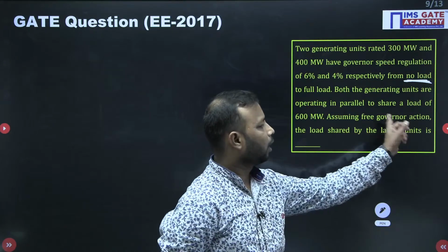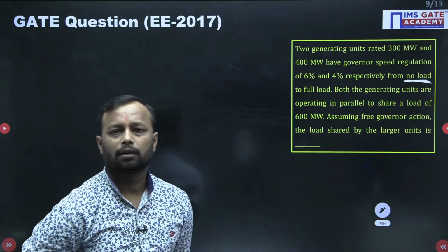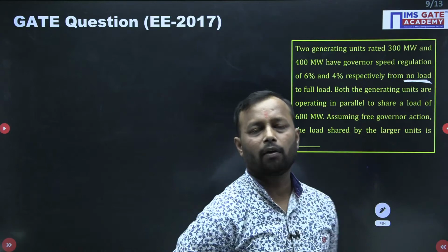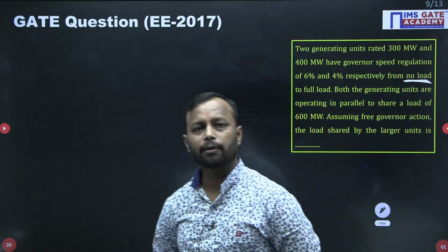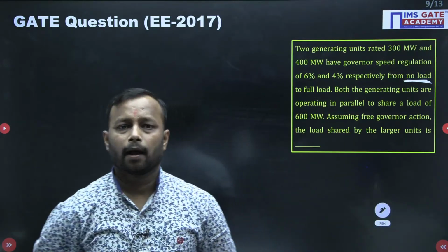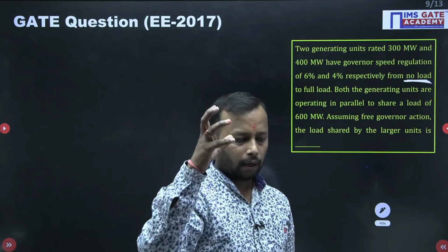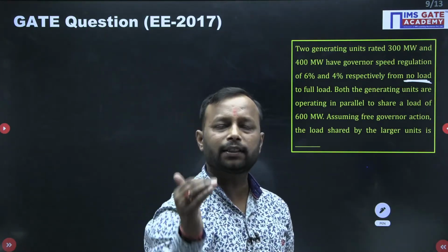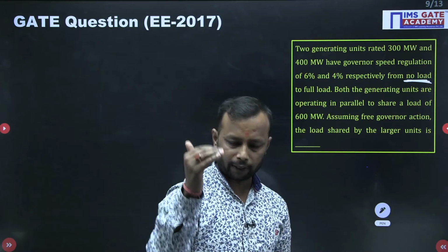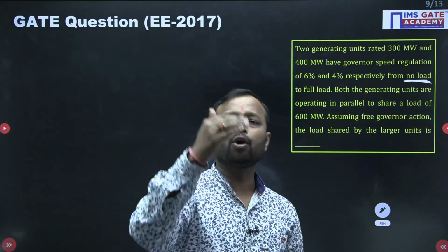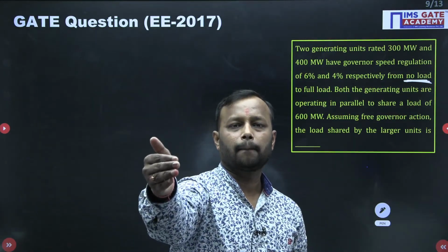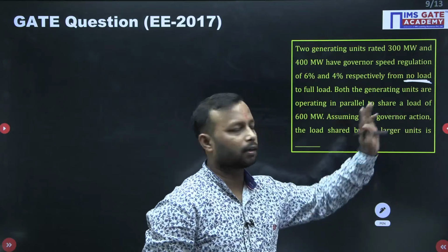So what is this governor action? What do you mean by this governor action? Governor action here means that if the frequency is decreasing or the speed is decreasing, then who is going to increase that? It is done by the governor.